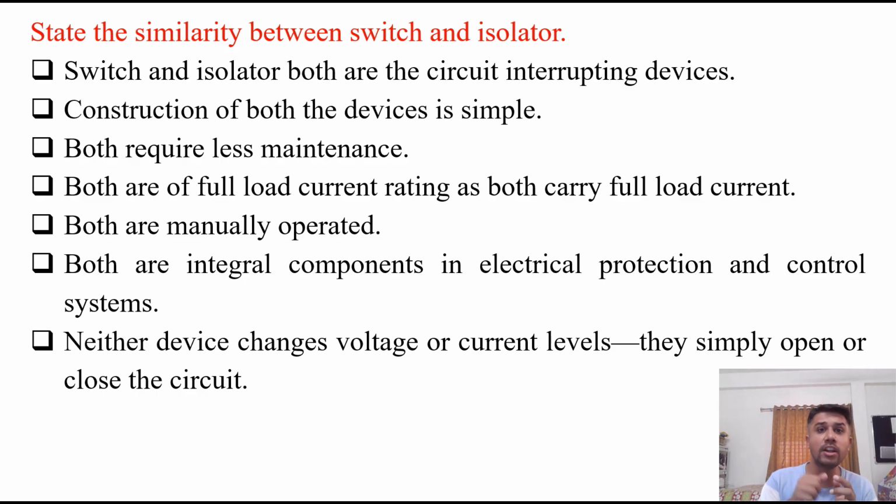Both are manually operated. Both are integral components in electrical protection and control systems. Neither device changes voltage or current levels. They simply open or close the circuit. So these are several points of similarity between a switch and an isolator.